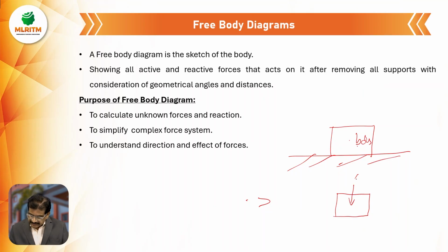One action is the total weight, and the other, according to Newton's law, is the reaction. Next we have to remove the support. I remove the support. Again we can show the geometrical angles and distances. Suppose there are any angles or dimensions, we can show them. That is called the free body diagram.